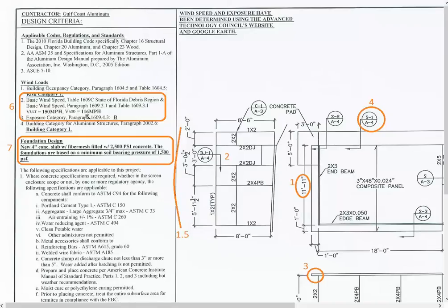Well, the 116 miles per hour is the nominal speed, and that represents the amount of wind that the structure must be able to withstand for 50 years without compromising its structural integrity. Now, the ultimate wind speed means the ultimate wind speed that it can sustain. But it's saying that at 150 miles an hour, there might be some compromise to the structural integrity of the building. 150 miles per hour and 116 miles per hour winds are pretty much standard for nearly all of Florida. Some areas, if you get down towards Marco Island, you'll get up into the 160, 170 areas.